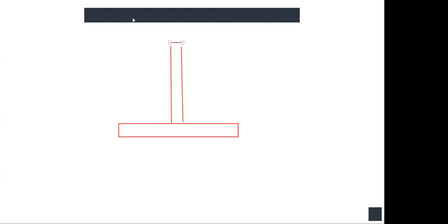Now, this particular side is my heel, and that's where your back fill will be acting. And the distance was given as 3.1 meters. I know that my total height is 5.5, and the height of this base is 0.5. But for me to get the vertical weight of my soil, it is area times the unit weight of the soil. The unit weight of the soil is 18, times